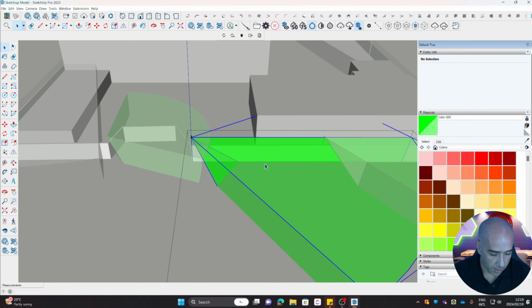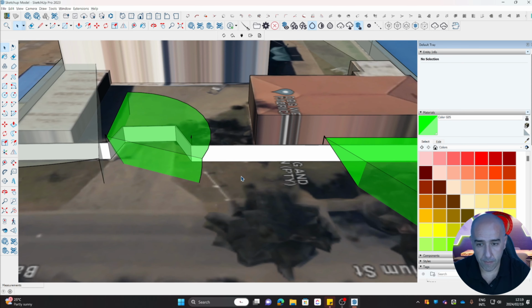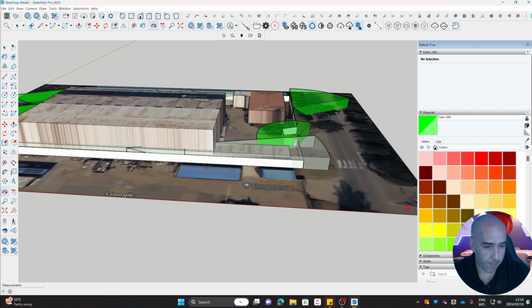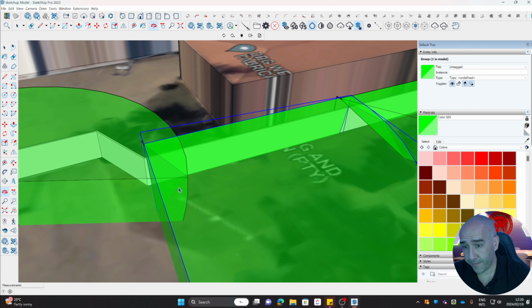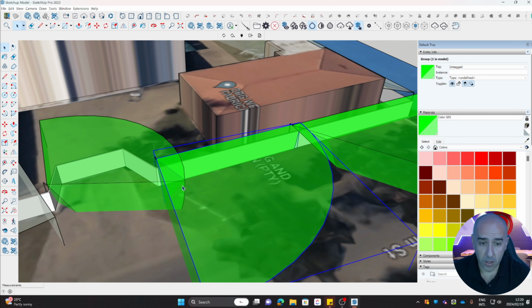So double click, I'm going to delete this view and I'm going to go grab the 4mm, and there we go. We've fixed the blind spot. No extra cameras needed. Changed the one camera to a 2.8, changed the 6mm to a 4mm, which means the blind spot is less, and now it's completely covered.